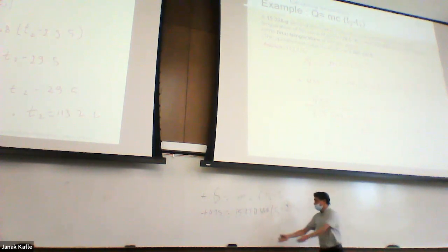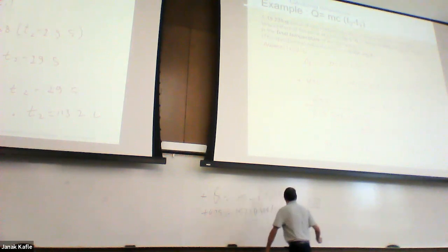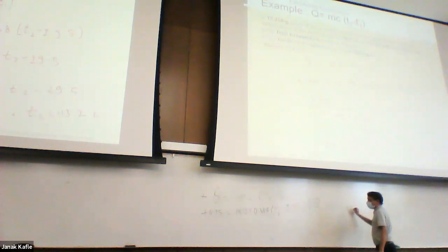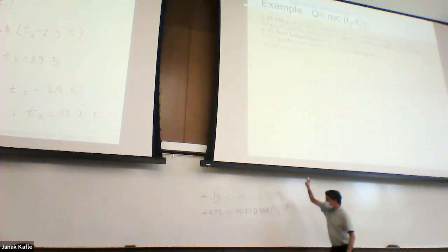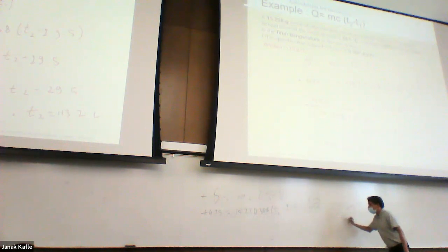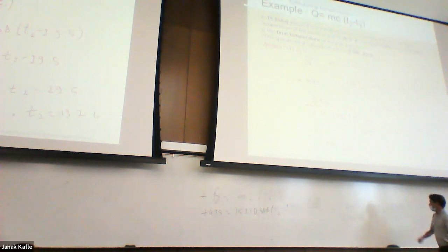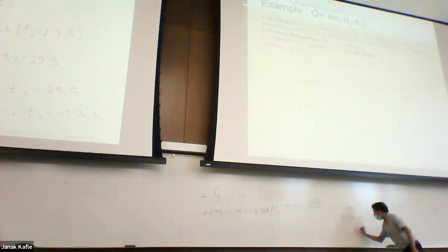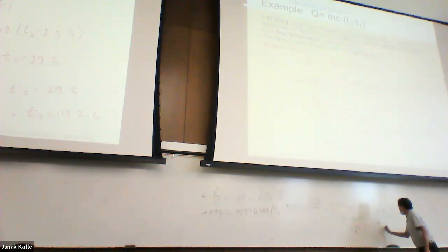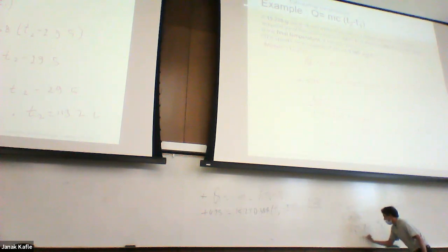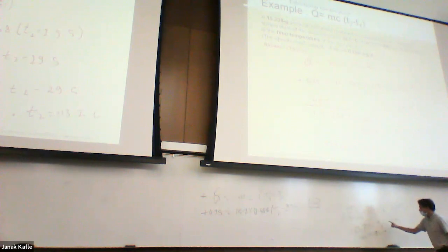I think you can easily do the calculation. So that is plus 495, divided by 15.2 multiplied by 0.388, equals T2 minus 29.5. Now you do this number in the calculator and that gives me 83.7. This 83.7 is a plus value, and that's T2 minus 29.5. So plus 83.7 plus 29.5 is equal to T2. The minus goes to the other side and becomes plus there. So how much is that? 113.2 degrees centigrade. Got it?